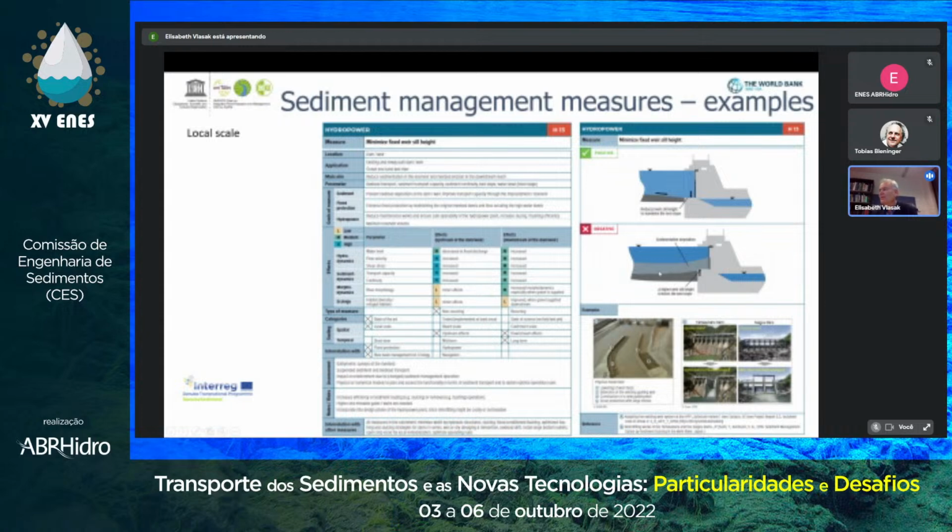You don't get rid of the sediment because this is a fixed point and the slope is not large enough. So we are advocating these days to rethink in planning and get the concrete part as low as possible. You have to think of the sedimentation and some other topics, but in many ways this is possible and described here. So minimize the width increase and minimize the height increase of the concrete.